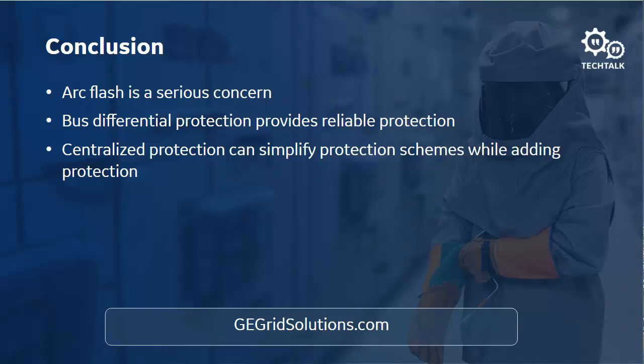Do you mean 3 to 5 cycles, not milliseconds, for breaker operation? I do. If I said milliseconds, I apologize. It is 3 to 5 cycles.